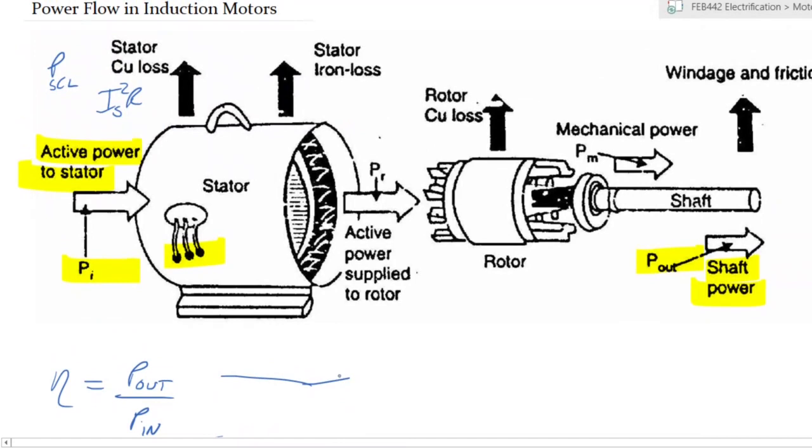Now, as you have current flowing through your windings, that current sets up your RMF. The RMF is a magnetic field that is set up inside the center of the stator. In order for you to have a magnetic field build up and move within the core, you remember we saw the laminations of the core, you would have losses due to the magnetic properties of the core itself.